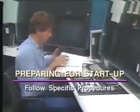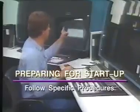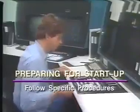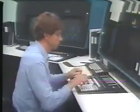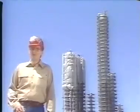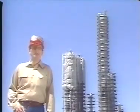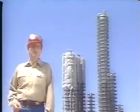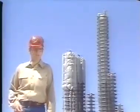Remember to make gradual increases in temperature and pressure when starting up a column. Rapid temperature and pressure changes can stress and damage equipment. Let's break from the video now and review the control procedures that are followed during startup and shutdown operations. Stop the tape and turn to Workbook Period 6.